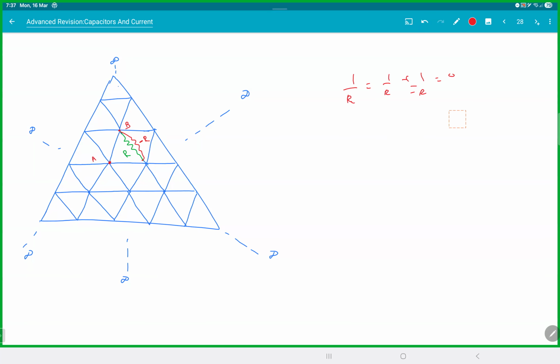So we can use something called a negative resistance. Now, physically it doesn't make any sense, but mathematically it's fine. It works. So we introduce a negative resistance to make it a symmetrical circuit. So that is the main idea there, right? So that 1 by R equivalent will be 1 by R plus 1 by minus R, and this would be 0, and you look at R equivalent is infinity. So this is an open circuit.